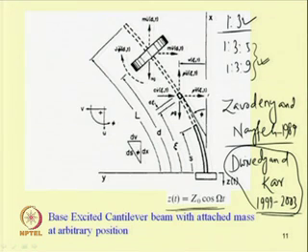So, now let us consider due to this vibration, a small element. In this small element one can write what are the forces acting. The forces: this is the inertia force rho v double dot (zeta, t), this is the inertia force in x direction. So, this is the weight rho g, and this is the inertia force in y direction rho u double dot (zeta, t).